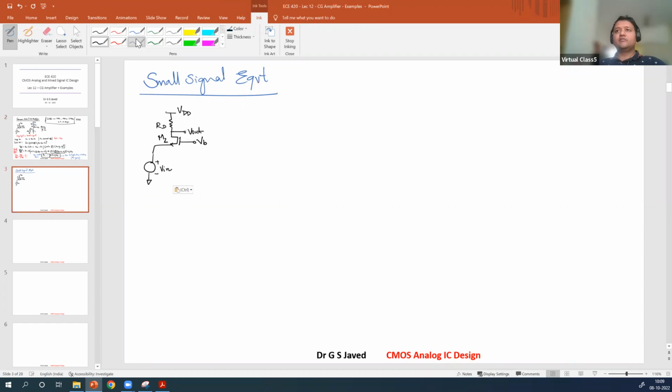So how do we do that? First thing we will start with is the RD. We have the NMOS device with its bias circuit VB, voltage Vout, RD, with VDD present here. There is the Rout of this device in the saturation region. Then we have the RS, which is going to come in the source terminal. Finally, the Vn supply.